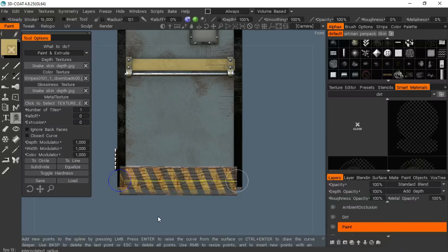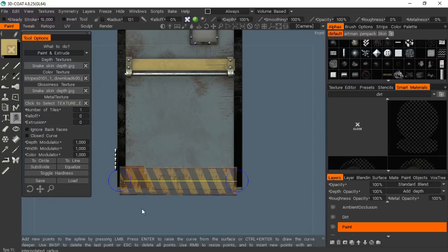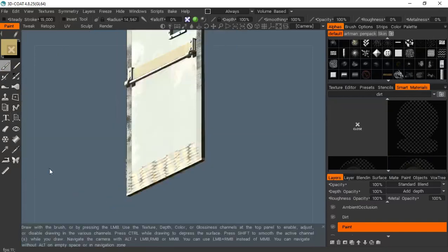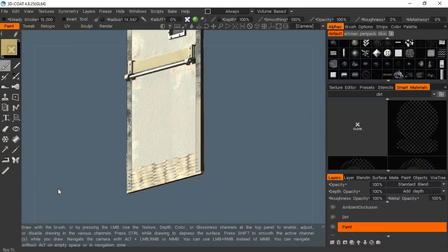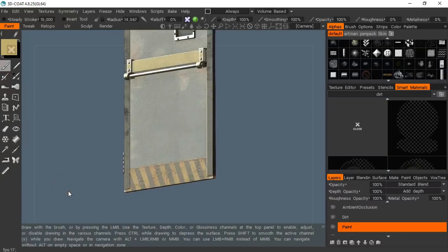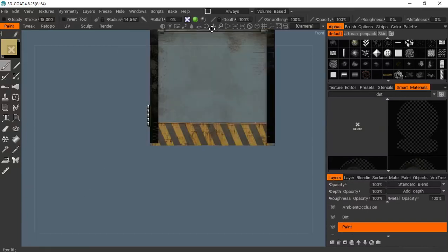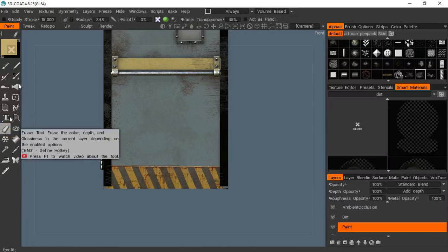Okay, press Ctrl Z again and uncheck the depth, because we just want the opacity and reflection. Now as you can see, it's showing now, but it's got this hexagonal type of specular glossiness. So a way to remove that, just press 2 and click your eraser.